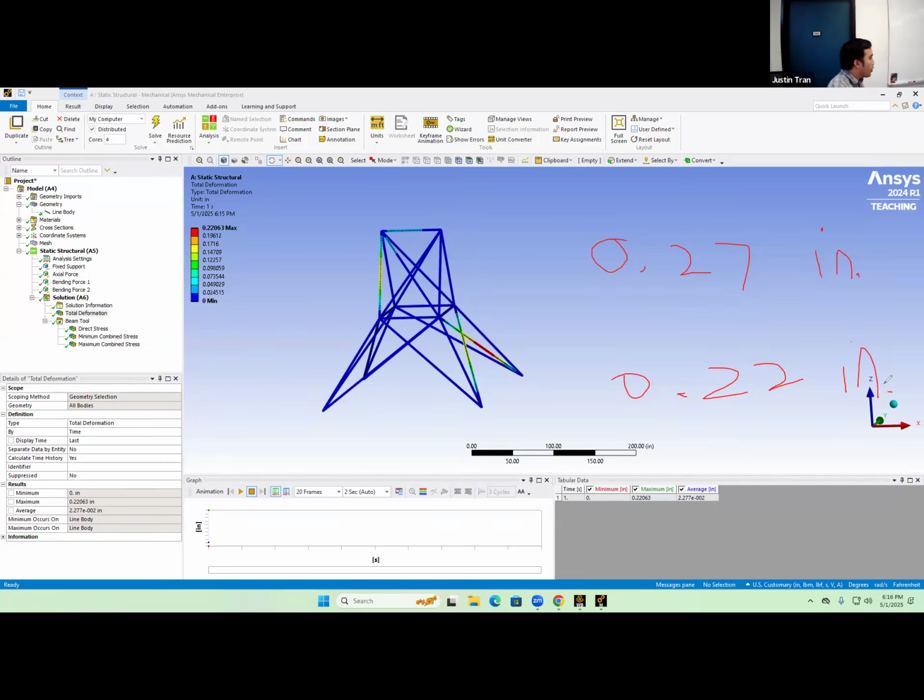So that right there is the stress stiffening effect in action. When you apply a compressive force, that causes the bending strength to decrease, and so that increases your deformation. When you apply a tensile force, your bending strength is increasing, and thus decreases your bending deformation.